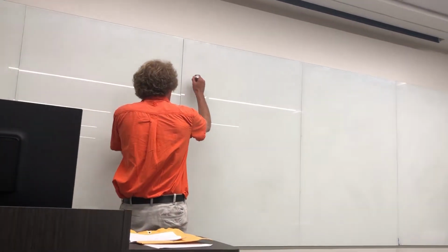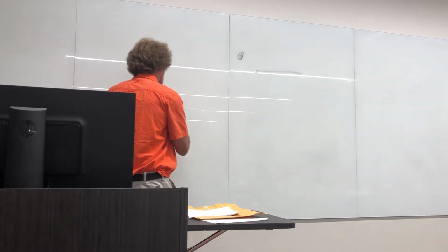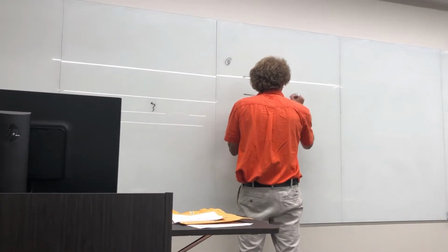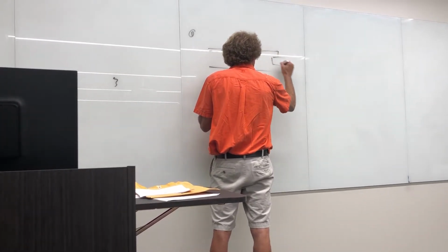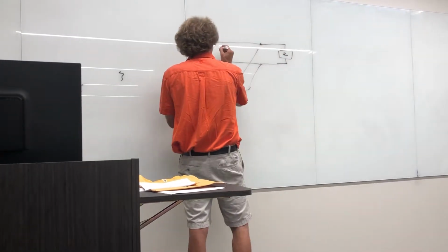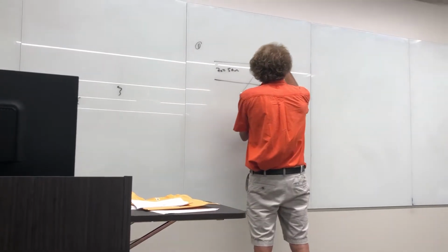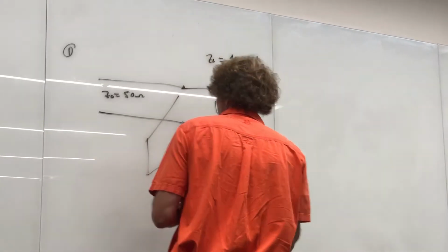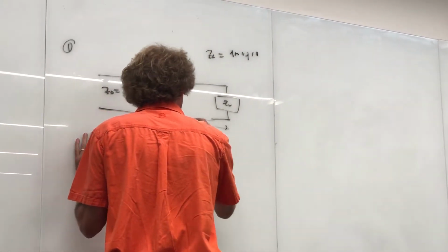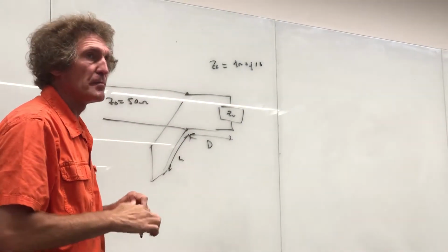So on the first problem, it's basically something that has a shunt, a short circuit shunt, and then you have a load. And Z naught on this one is 50 ohms. Here ZL is equal to 40 plus J10. And we want this length, and I believe I call this D, and this length, I think L, but I'm not absolutely certain. We wanted them in meters.